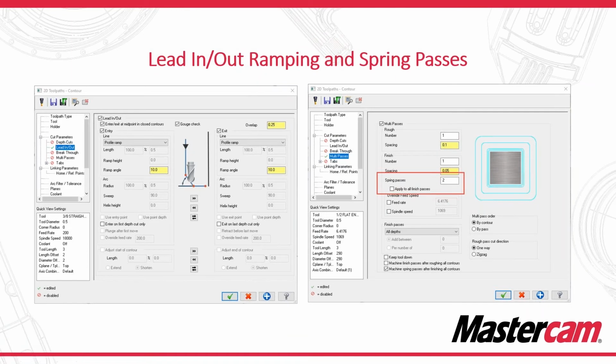All right, the next thing we're going to go over, this is just a quick one here, is we have a new option for our simple 2D toolpaths for lead in and lead out. And then also in multi-passes, we have a couple new options for spring passes. I'm not even really going to go over this because it's very simple. Basically, before, if you had multiple Z cuts, your spring pass would only take a cut at the final Z depth. Now we have the ability to tell spring passes to finish after all the contours, apply to all the finish passes, just a couple extra options inside a spring pass.